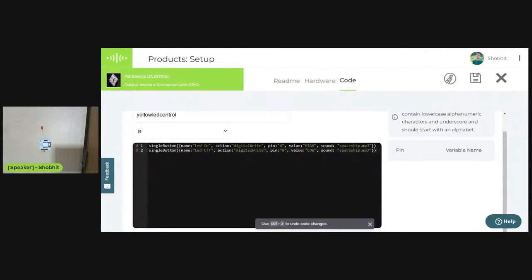It is a digital write function. I'll tell you what digital write is in short. See, in the Bolt Wi-Fi module, there are majorly two kinds of pins. One is analog pins, and another one is digital pins. Usually, whenever you need to connect output devices like LEDs, buzzers, or any such components, we connect them to digital pins. Digital pins work as a switch only. They are used to either turn on something or turn off something.